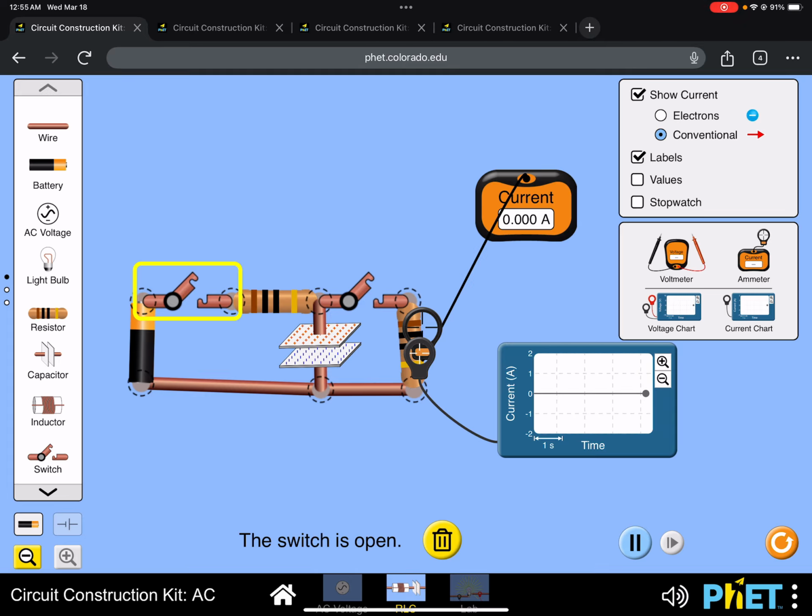I know that the voltage across the resistor is going to equal the voltage across the capacitor. And so the capacitor is going to start to discharge into the resistor. And as the capacitor discharges, the voltage should drop. And if the voltage drops across the resistor, then the current going through the resistor will decrease as a function of time. So let's just see it. I'm going to close the switch now. And we see here that the current clearly decreases until the capacitor is fully discharged. All right, so that's the answer to that problem.